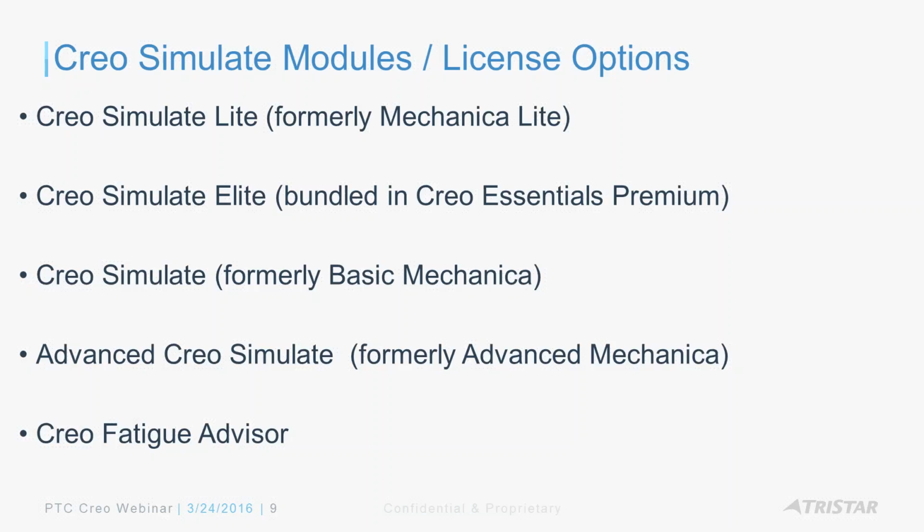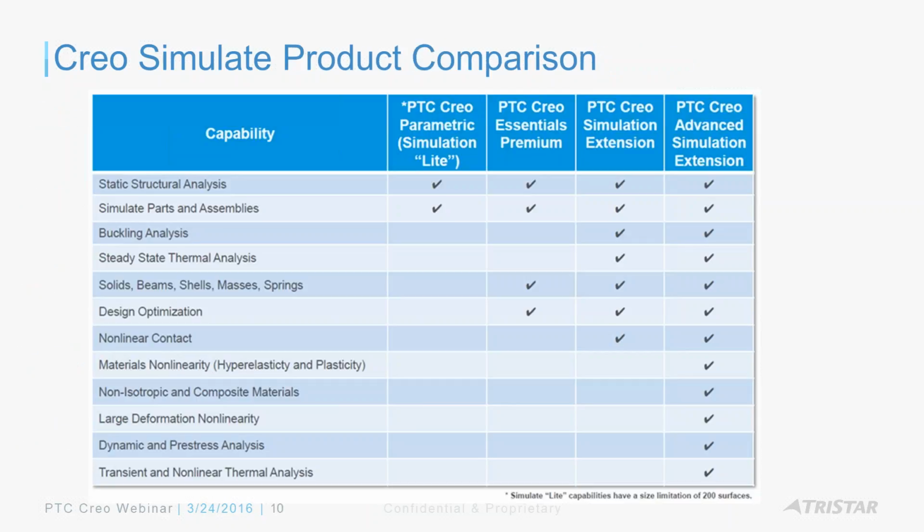There's also a Fatigue Advisor extension that can sit on top of either the Creo Simulate extension or the advanced Creo Simulate extension, that allows you to do durability studies. It gives you the confidence of life, essentially telling you after how many cycles of loading you are going to see a crack. When will a crack start to grow? That's what it's going to give you. It's a very basic fatigue analysis, which requires a static analysis as a reference analysis.